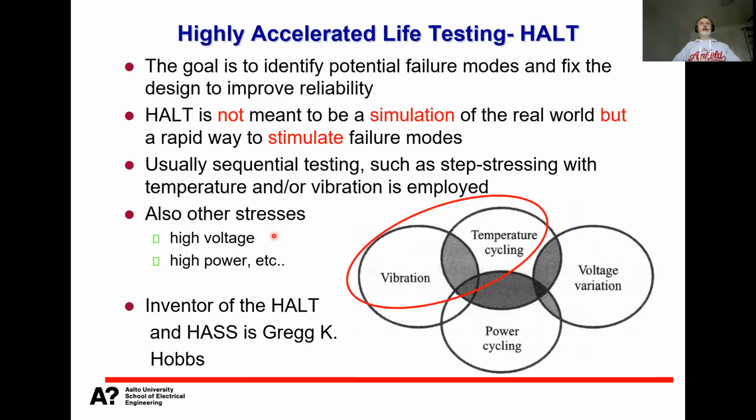So what is this highly accelerated life testing, HALT? Basically the idea is that by whatever means, and whatever means here refers to whatever stresses and as high stresses as possible, we try to identify potential failure modes and fix the design. So we again think about what could happen, but we are not thinking about how reasonable these stresses are.